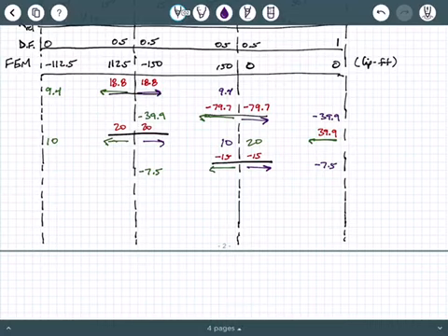So now, what have we just done? We've just unbalanced D again, and we've just unbalanced B again. So you may be thinking, well, what are we doing here? This just keeps going back and forth. I keep balancing one thing, and then I take something else out of balance. Well, if you notice the unbalanced moments, what are they doing with every iteration?